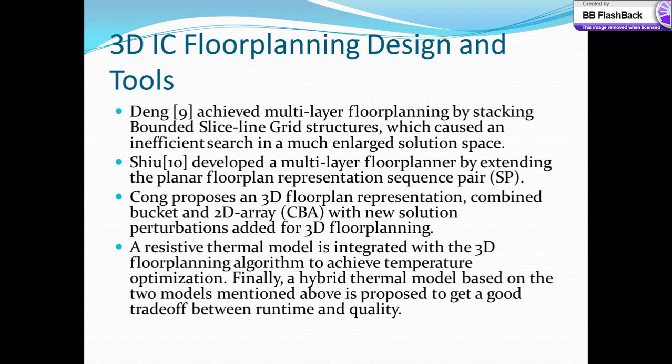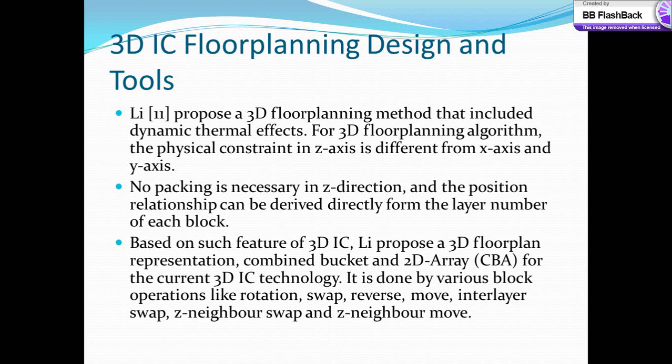Coming to floor planning design and tools, there are a bunch of papers which extend the concept of 2D floor planning into 3D. Lee in his paper proposed a 3D floor planning model that included dynamic thermal effects. His work is based on the idea that the packing in the Z direction is not going to be the same as in the X or Y direction because there are no vertical transistors.